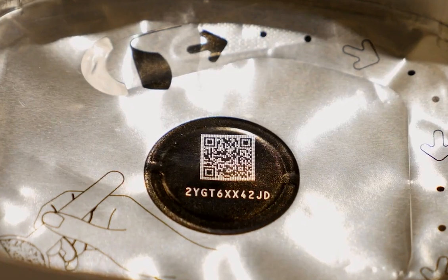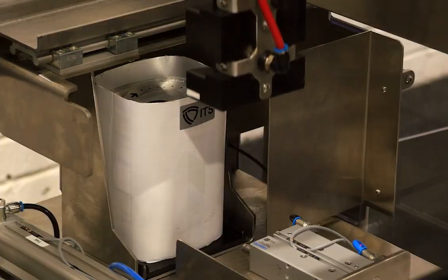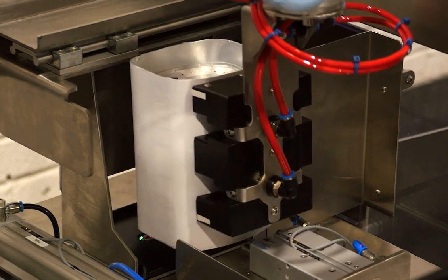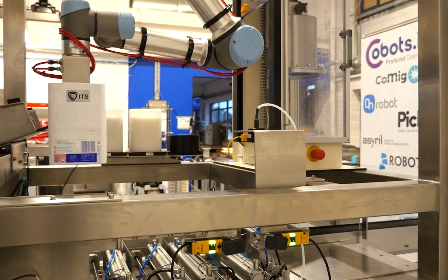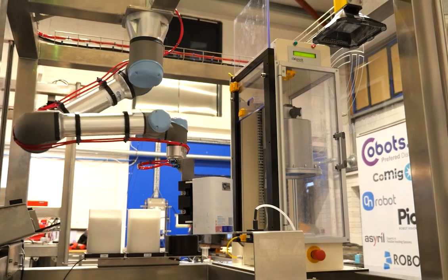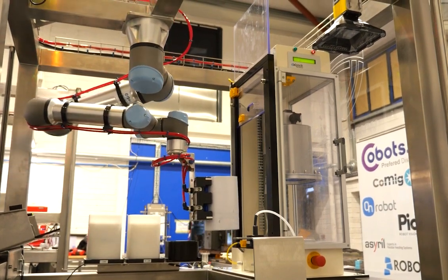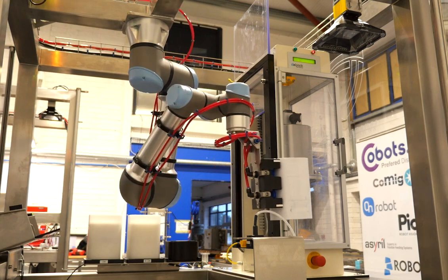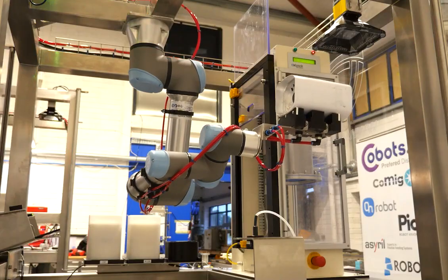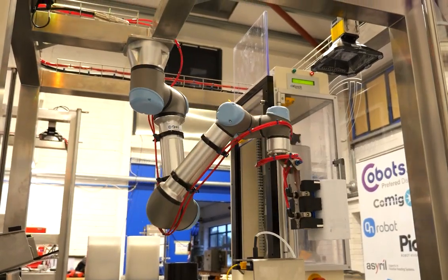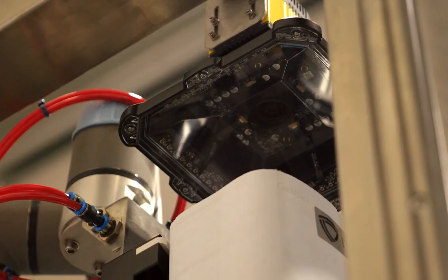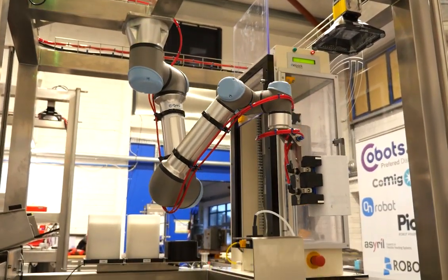And then, based on those, if they're a pass, the robot will take the part to a seal integrity tester, where the seal will be checked, and if that is a pass, the part is taken to the outfeed and passed out to the operator. So you can see the robot presenting to the scanner to read the barcode. It'll then also present the part to the same scanner, which will read the data matrix on the top of the foil seal. It then moves over to the pressure test, where it will test the integrity of the foil seal on the top of the canister. And based on that output, it can say whether a part's a pass or a fail.